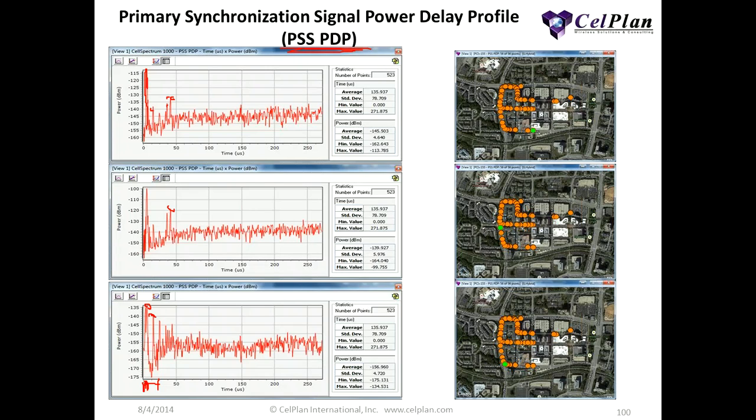What is happening today is that operators generally want more capacity, so they say, let's use normal prefix. Well, the cyclic prefix can be dimensioned per cell, so it doesn't need to be the same in all cells. We have done measurements with commercial operators, mainly in our area, and we found that in many cells they have multipaths larger than the normal cyclic prefix they are using.